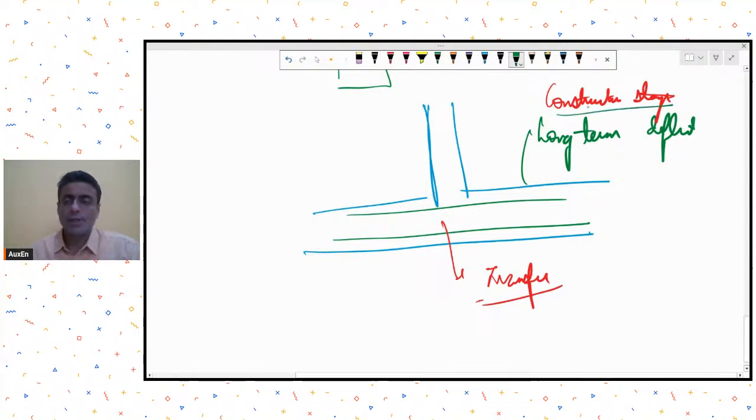So you should be aware of the construction stage analysis and you should try to do this kind of an analysis. Typically a software like ETABS will do it for you. You should be very careful about the long term deflection. Why so? Because with any changes in the deflection over a period of time, the behavior of this floating column or the movements in this floating column will also undergo variation. So you have to be careful about it.